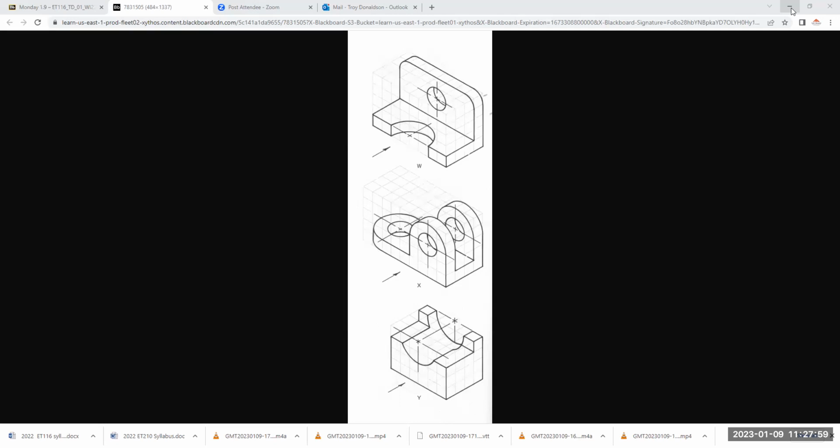Okay, so remember, you got to load them before you can use them. There's a lot of ways to do this, and we will get into layers and layer control. But in the beginning, if you want a hidden line, like I'm going to put a line in here, and if I want that line hidden, the way I do it is I just draw a regular line in, because I don't like going up and switching them because I'll forget.